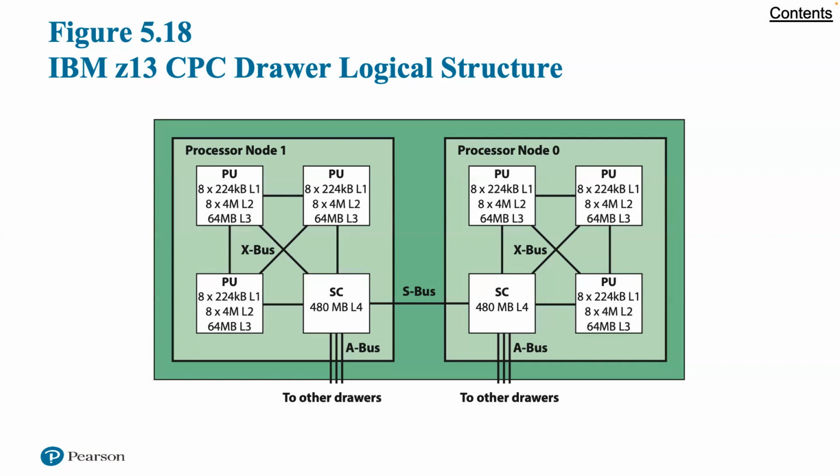Further, the L3 cache is most efficiently used if it always maintains the most recent version of any L2 cache line. Going from L3 to L4 is a lower speed off-chip transmission, and here a write-back policy is preferred to minimize traffic. Similarly, write-back is preferred going from L4 to main memory.